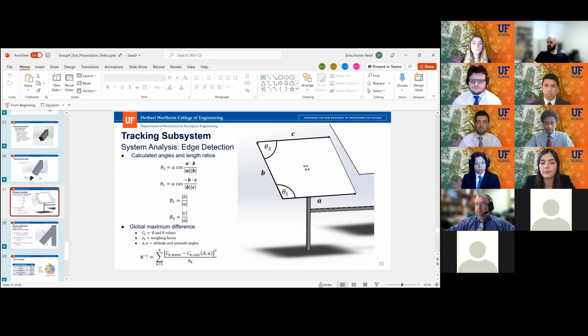I did love your wind equations, and it was great that you calculated the stresses and whether you would meet the stresses. But since you've done all that work, maybe you should just take a peek at what kind of deflections you are going to see at those wind speeds. If you were responding to a constant wind, then your closed loop system could account for that. But if you have a gusty wind where it sets up a resonance, then you're probably going to get some kind of instability in your feedback.